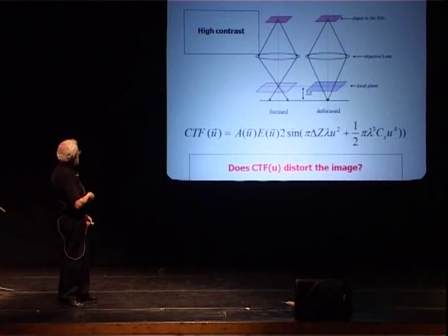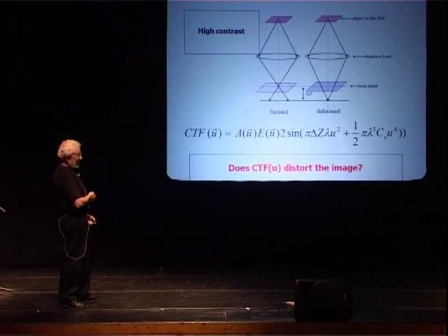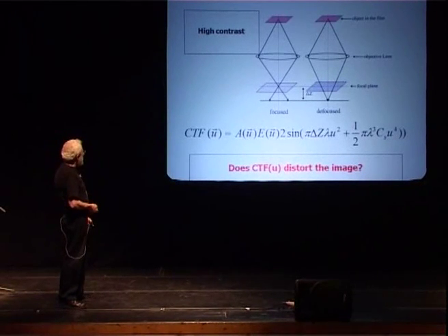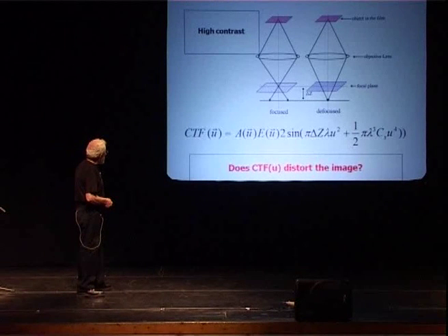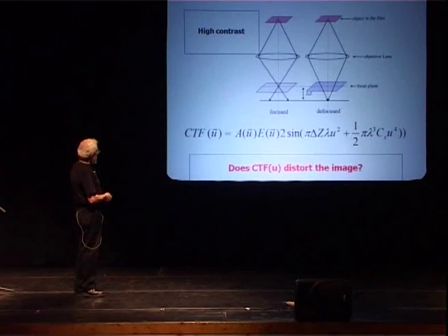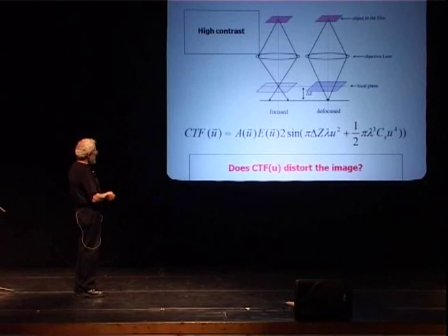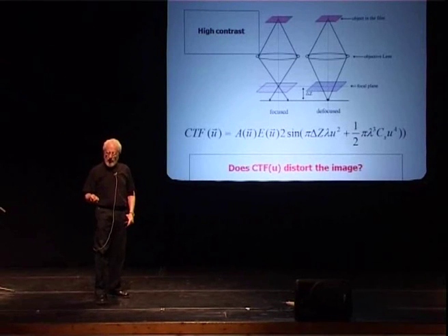The way you look at it is schematically like this. You don't focus the electron beam on the surface because there's very little contrast. You defocus the beam and focus it well below, about 25 microns below the plane of the surface, and then you can get some contrast. This comes with some limitations. Those limitations are described by this contrast transfer function, which is a function of the length scale that you want to see and the defocus distance. So if you defocus by about 25 microns, it turns out that one is quite sensitive to length scales in the 10 to 20 nanometer regime.